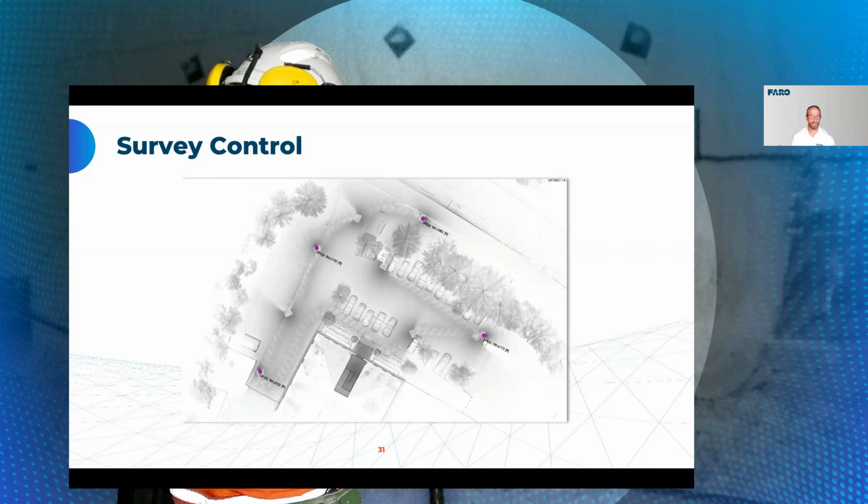So before you start any survey, or in this case, a scan, we always get a lay of the land, right? You want to make sure that your survey control is spread throughout the scene, providing the most accurate final result. Generally, in survey, the more points you have, the more accurate your overall data set is going to be. In this example, we laid out just 4, but this was just a backdrop for what we were scanning, which really was the facade of the building. And by spreading our points evenly throughout the scene, we would increase the accuracy of every single point on that building surface.